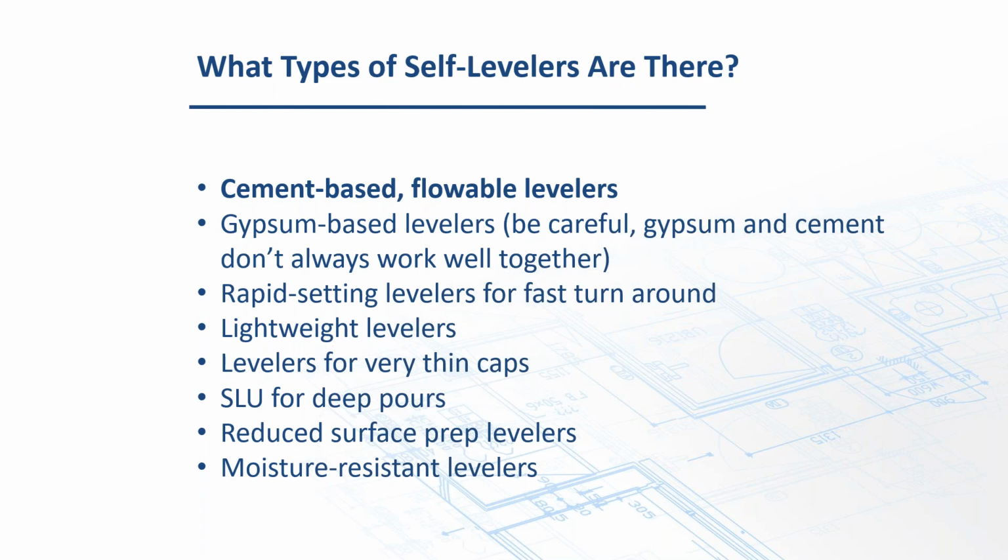We have SLUs, or self-levelers, for deep pours. We have one that'll go 4 inches without any additional aggregate or anything like that. So you really have to need that. That's a lot, but we definitely have some for deep pours. Surface preparation can be critically important to self-levelers. There are also ones out there that are shrinkage compensated, and the amount of prep is not quite as high as the ones that are not calcium aluminate based.